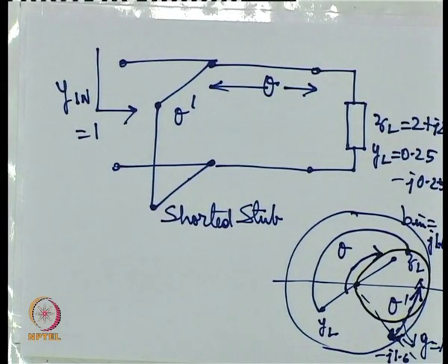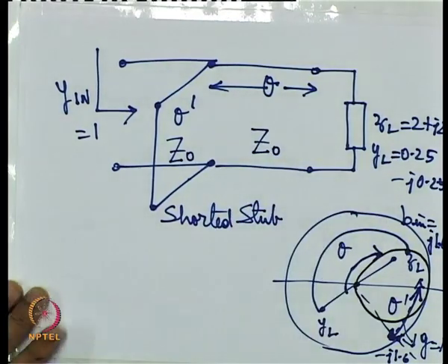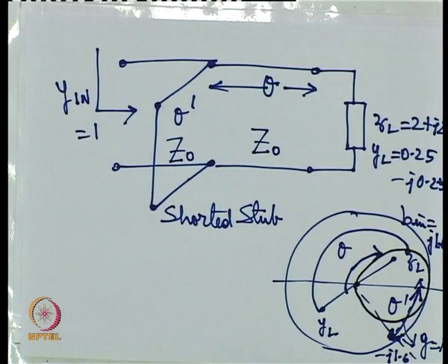So this is how we can do the impedance matching. The advantage, as I said here, is that the characteristic impedance of all the segments is the same. I have shown two methods of doing this, one using a quarter wave transformer and the other using normal transmission lines along with shorted stubs. The method that you choose is up to you, but keep in mind the realizability of the method, and whichever method you use should contain the minimum number of segments. Thank you.